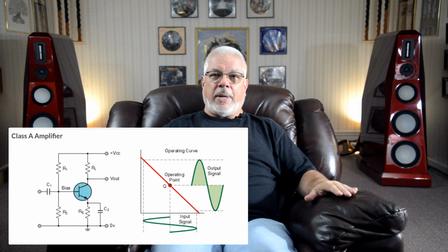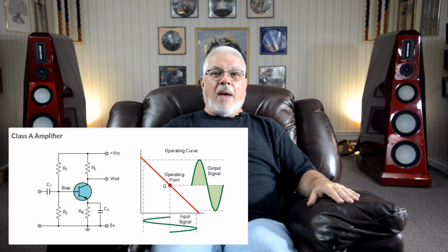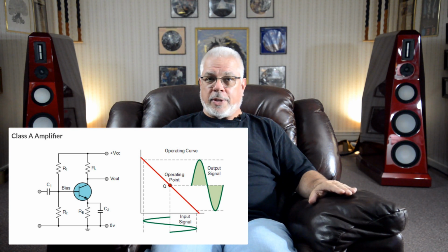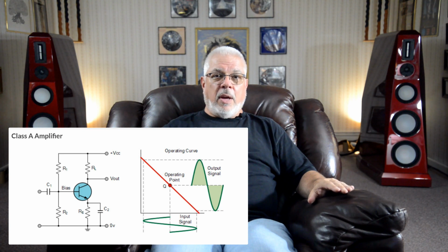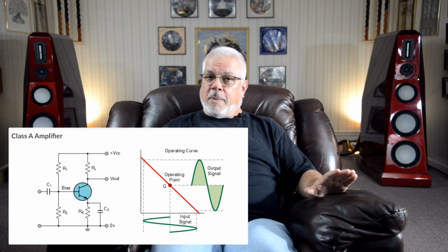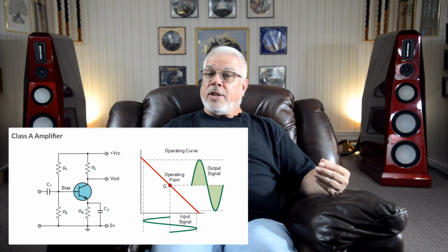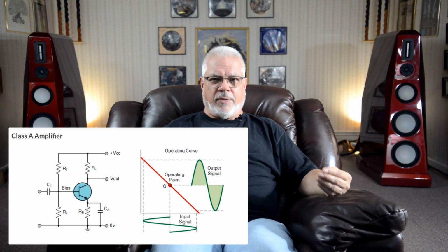In Class A amplifiers, neither half of the complement ever switches off. They are on constantly. Neither half of the push-pull complement ever shuts off nor throttles back from full current draw, even during the half of the cycle that it is at rest. This is achieved by the application of a forward bias current applied to both complements, so that even with no drive signal, each complement remains fully on. Because they have the same amount of current running through them at all times, under duty and at rest, they draw as much power at idle as they do at full volume.